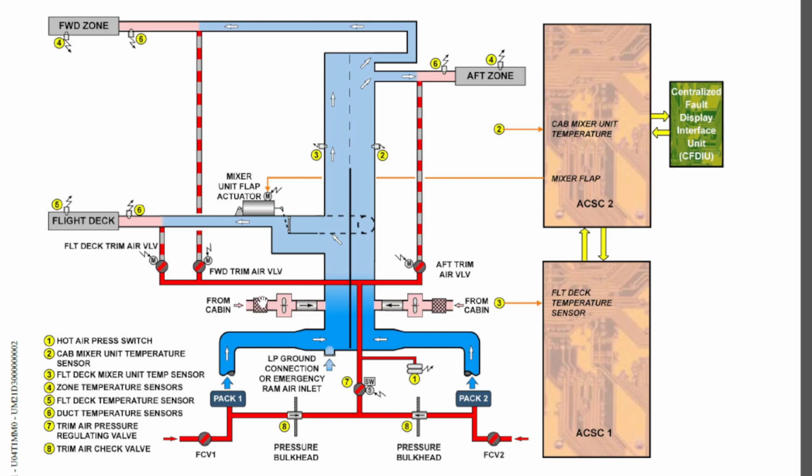And what you see here is the filter. There are two filters, so you have two recirculation fans and two filters. These are cylindrical type filters. You will see these recirculation fans and the filters, and this is a check valve. You will see these parts when you remove the aft partition wall in the forward cargo compartment. Only then will you have access to these components, right?